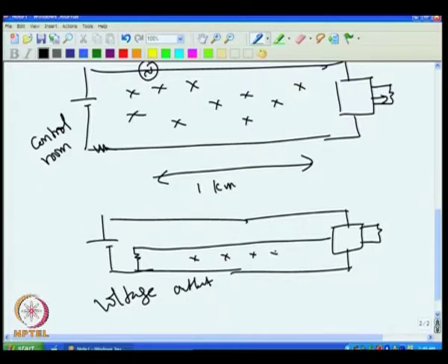If it is a voltage output like this, the problem is that there is an enormous amount of loop here in this area. So, this will be sending some voltage and that is supposed to get here. Suppose this sends 1 volt and you expect to get 1 volt, leave alone the loss taking place on the wire. But the voltage induced in this loop due to an external changing magnetic field will appear along with this.